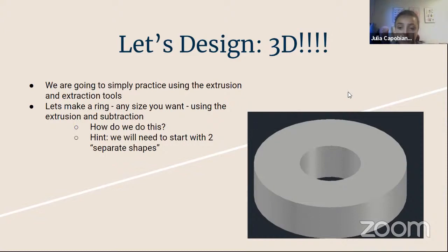So I had to use AutoCAD to 3D print rings, and something that you have to keep in mind when you're doing subtractions like this, and if you want stuff to fit in a certain space, so like this hole right here is supposed to go over a peg on one of our devices, you have to think of tolerance, which I don't know if anyone knows what that is, but basically it's when you 3D print stuff and you set a hole or even a shape to a certain size, there's a certain tolerance level, which basically means that there's a certain degree of variation that happens.